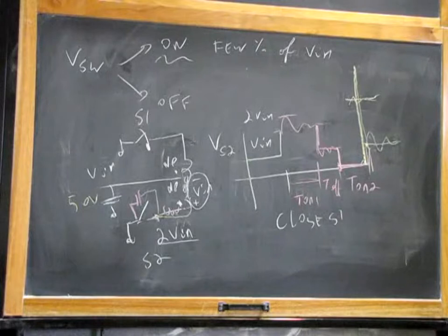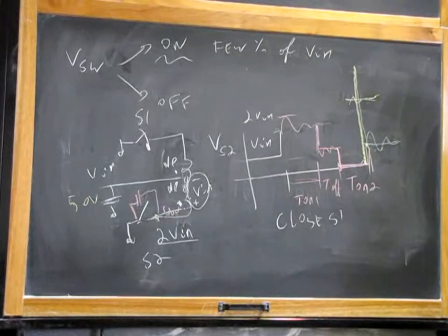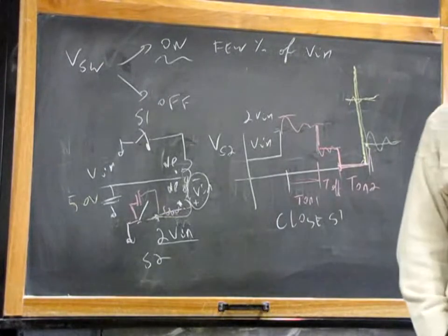These audio amplifiers in a car, in order to deliver power, even reasonable power, like 50 watts, 100 watts or so, they need voltage. They need 30 volts, 50 volt supply voltage. In your car, you don't have 50 volts available. The standard is 12 volts, 14 volts if your engine is running, 10 volts if your battery is low and your engine is not running. So, the only way to boost up the car voltage is not to use a boost, because a boost is a single transistor, not a so powerful converter.